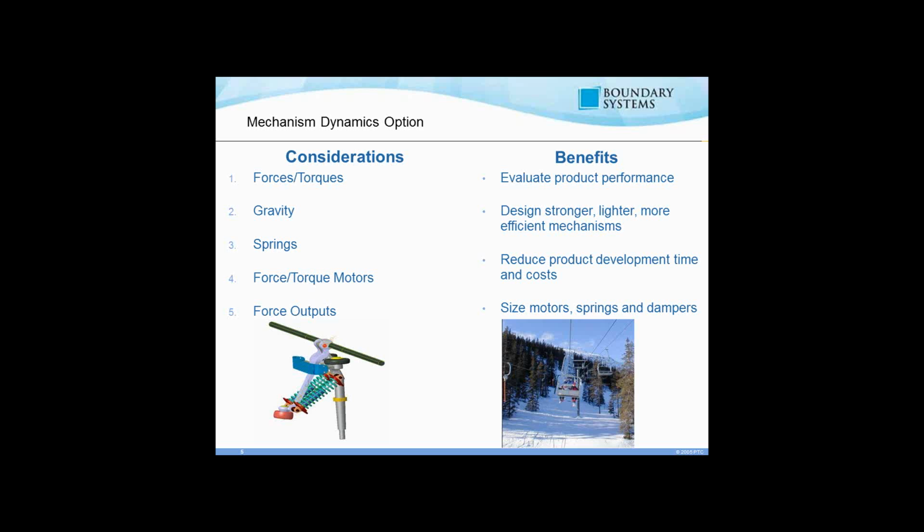And you can define servo motors that basically either move linearly at, say, a linear rate per second, or an RPM, for example, rotations per minute. And you can analyze the kinematic behavior of your mechanism, how fast particular areas of your mechanism are moving, what the position, velocity, or acceleration of those parts of your mechanism are. Those are the kinds of things you can do with the base mechanism module.